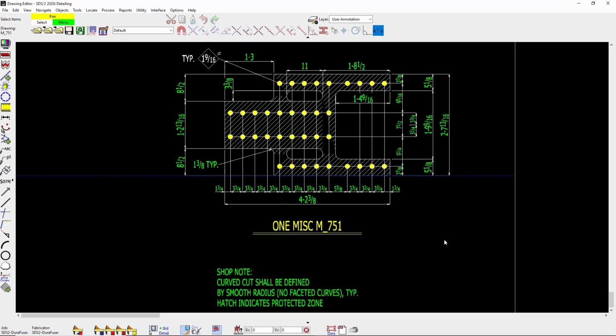Often the moment frame sizes are dictated on the engineering side for drift requirements, as far as getting the building stiff enough so that it doesn't flex too much during an earthquake. And typically it's difficult to meet those requirements with small shapes, but there's not a reason why we can't go that small.